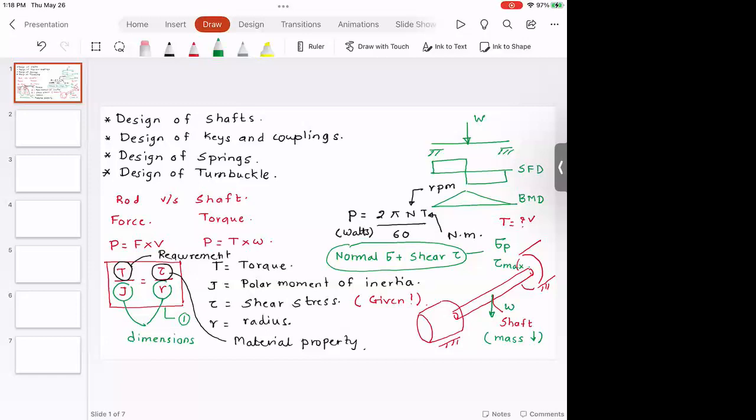So when we design aluminum parts, we have to design them so that they are safe at that orientation. All these theories of failure try to justify or come up with some type of logical argument on the failures that are observed in engineering. One thing I want you to understand is that these failure theories are all good and valid when the loading is slow. The theories of failure change when the loading is quick, which means if you have high strain rate or dynamic loading, the failure theories that you studied will no longer be valid. And there are additional considerations that you need to take into account when you study failure under dynamic loading.